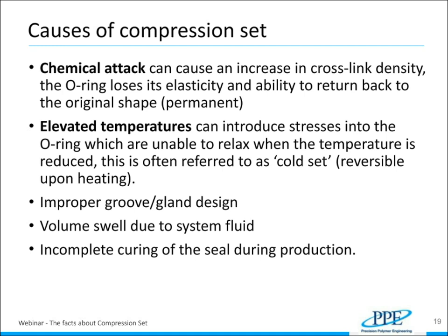The first is improper groove or gland design. If you overstress an O-ring, for example, while it's in the groove, you'll get increased amounts of observed compression set. The same with volume swell. So if there's been significant amounts of volume swell, ingress of fluid during the application, this will lead to compression set.